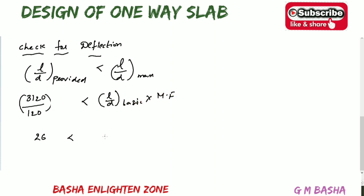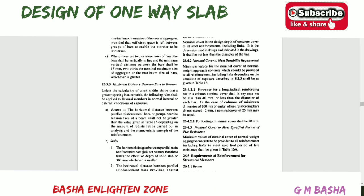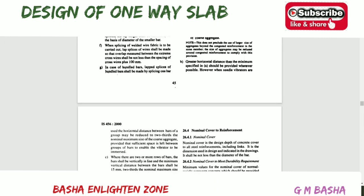What is the L by D basic? L by D basic for simply supported slabs is 20 into the modification factor. What about this modification factor? It is calculated by using one curve in your Indian standard, which I will show you here, which is on page number 39, I think 39 plus 13, 51.